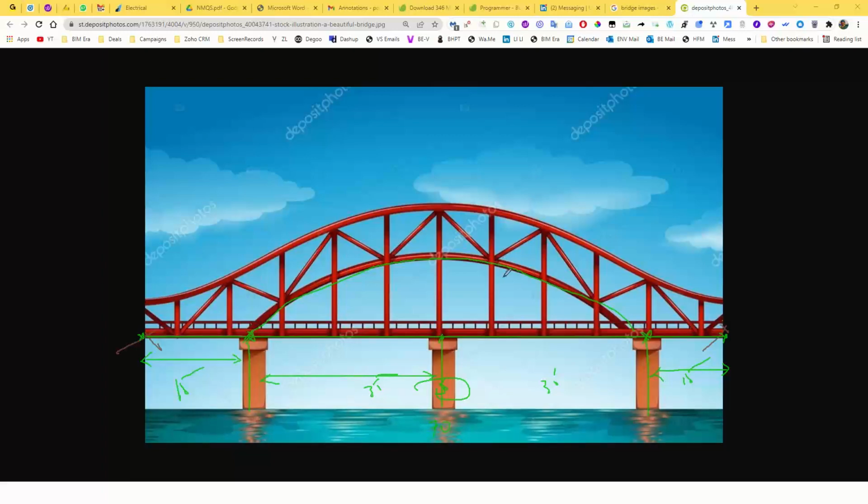Let's see, whatever it is, if it is a rectangular shape, or a square shape, or an elliptical shape, whatever it is. I already have a family, so I want to convert this curve into the adaptive component. Okay, I'm done with this. Now I need one more exactly the same, so I want an offset of this. When I use an offset, it brings one to another up to some extent.